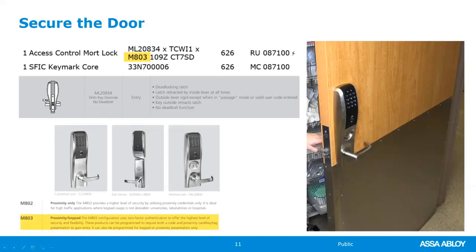Mortise locks were chosen by the owner for this project because with a Mortise lock in a hospital environment, you have a lot more functions to be able to choose from. They're durable. They're easy to have their locksmith maintain. If a spindle breaks, they can replace a spindle very easily. Any of the little springs or parts, they can replace or repair those themselves. And so Mortise locks are the standard throughout this facility. There will be some cases like patient bedrooms where hospital latches, the cylindrical version of the hospital latch, are used, but any high frequency door, any of the main points of entry will be Mortise locks.